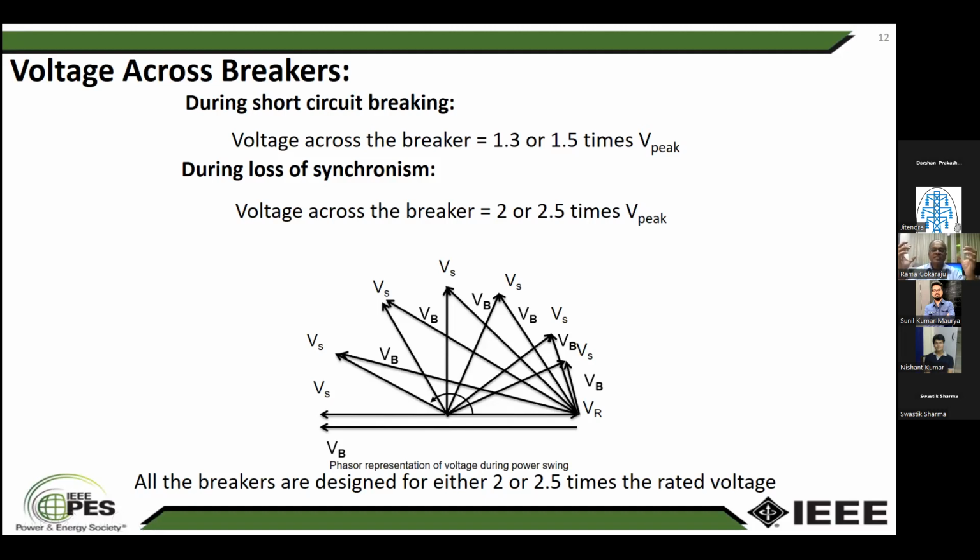So when a pole slip happens, 180 degrees is going to correspond to this angle of separation between the two ends. So that's why we wait until this phasor rotates, and between 270 to 360 degrees is when we do the separation, so that the restriking voltage is not very low.